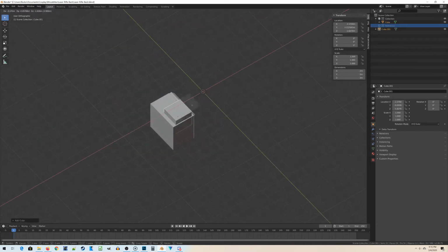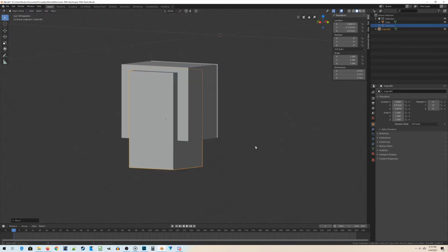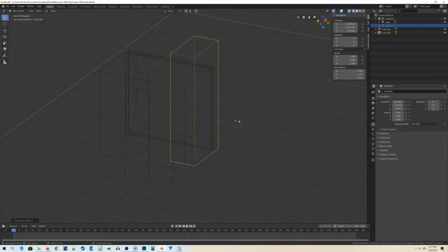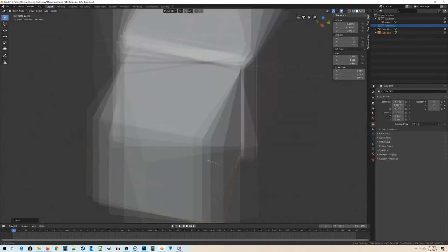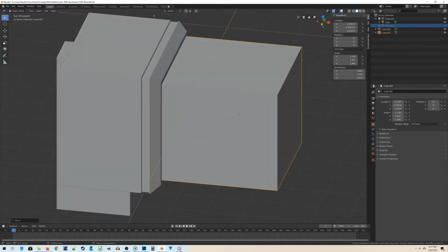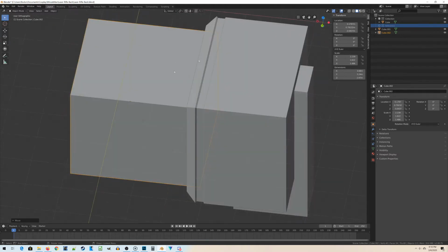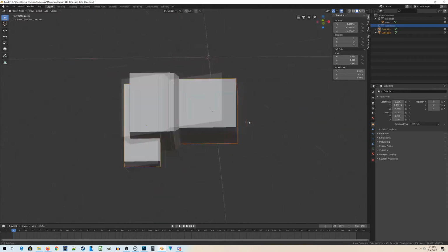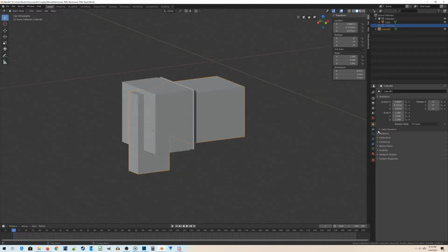All I'm going to do is create a new cube. I'm going to scale it up to where proportionally it looks right. And then I'm going to add one more cube. I'm just going to duplicate this one. I'm going to scale this one so that it's inserted into the piece, the rough size of the inset area in the back. Obviously this thing's much bigger, but the piece where it's overlapping, intersecting, is going to be cut out and left a little bit of a cavity there. So I want to join the 2 pieces that we're going to actually cut out together. So click on both of them, Control J, join them together. We're going to name them cutout.